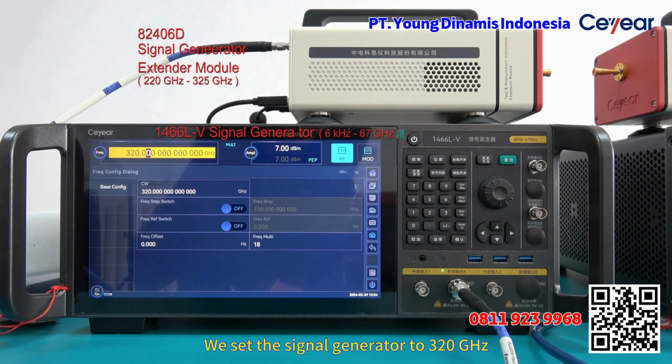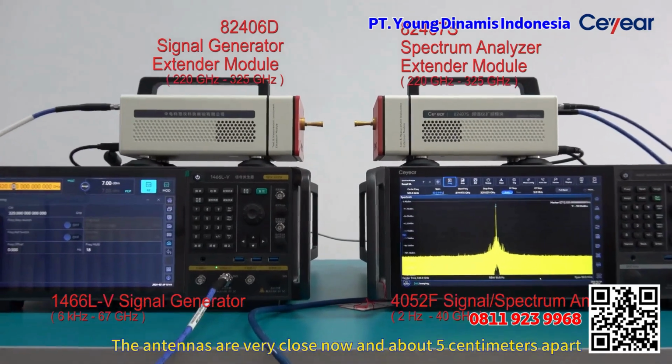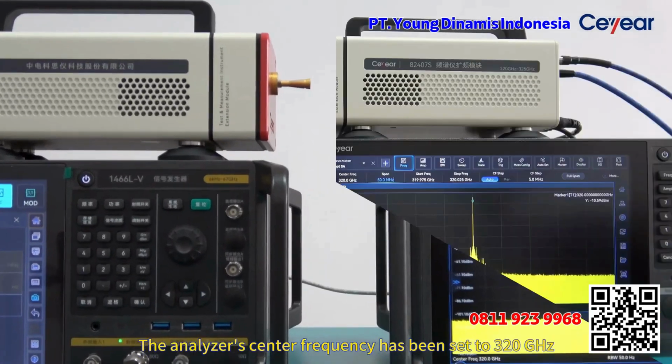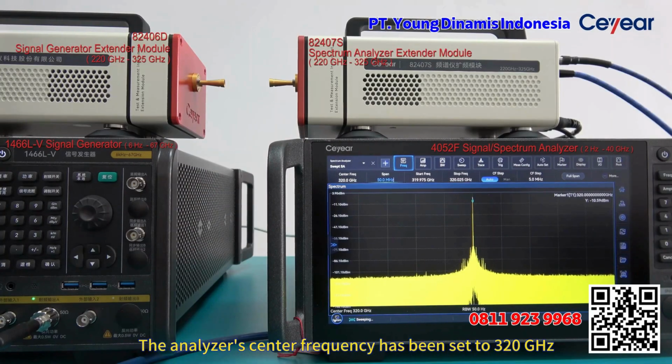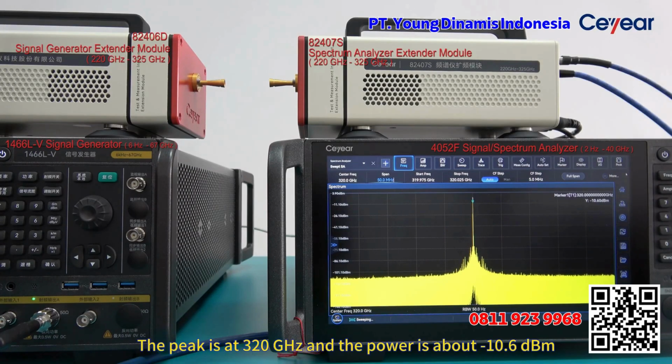We set the signal generator to 320 GHz. The antennas are very close now and about 5 cm apart. The analyzer's center frequency has been set to 320 GHz and RBW to 50 Hz and span to 50 MHz. The peak is at 320 GHz and the power is about minus 10.6 dBm.